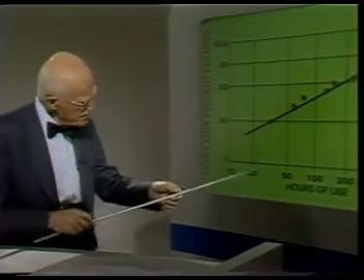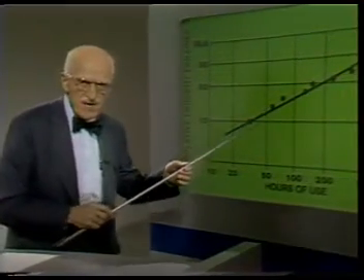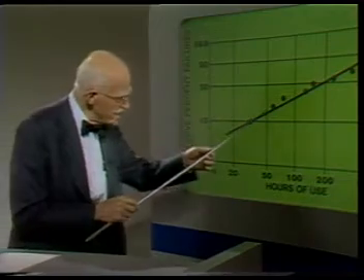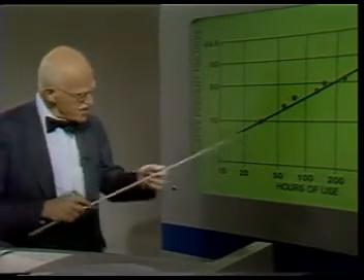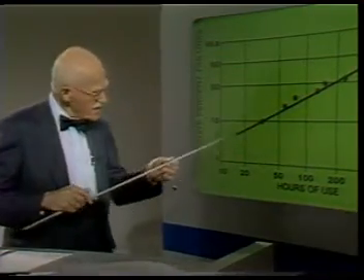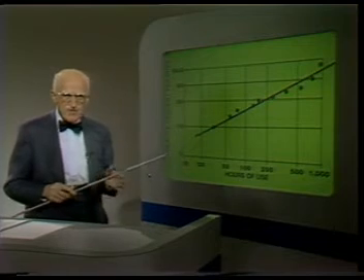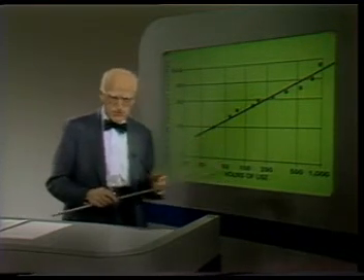A second unit fails at 58 hours. We plot that on the 20% line, since 20% have failed cumulatively. We continue charting until all have failed. A curve through the points will approximate a straight line. From the curve, some useful estimates can be made. For example, what will be the service call rate during the warranty period? What will be the need for spare parts?